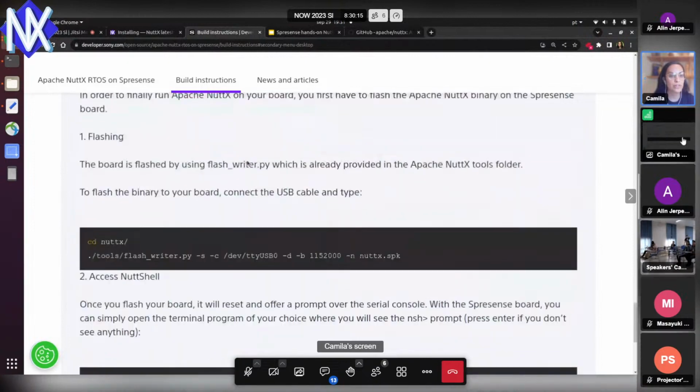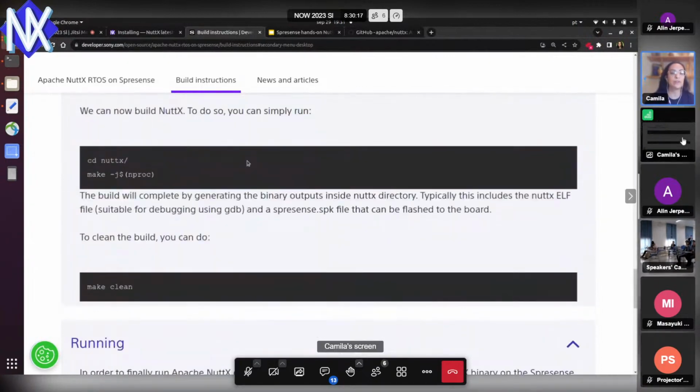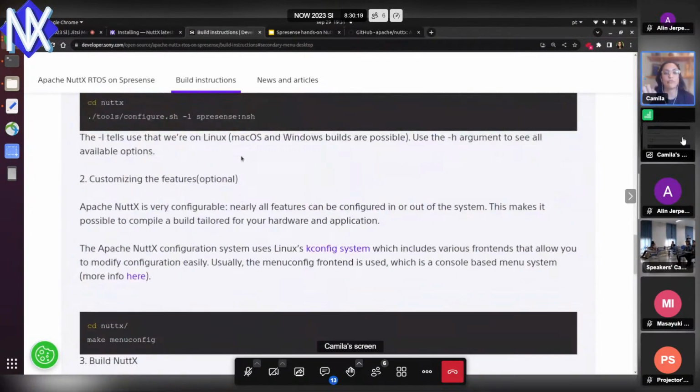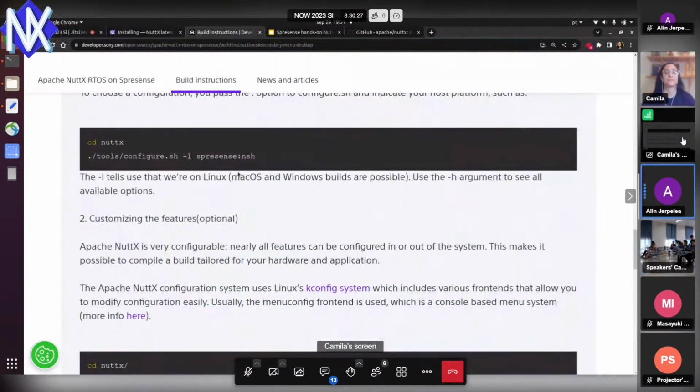The configuration didn't work, because the configuration that we did now for the NSH is exactly to be able to have... Yeah, I did the same configuration on the console. It may be the bootloader version. You may have to update it from Developer World. You were correct, with a different version. Error regarding the flash writer.